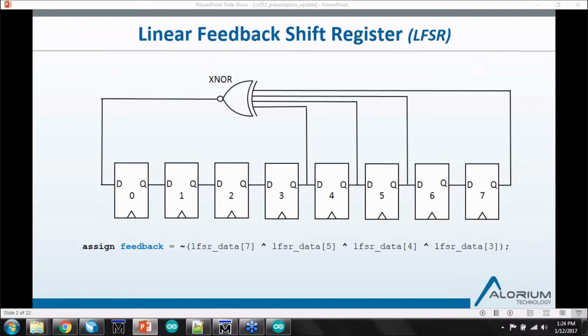For example, in verification or testing for chips, a lot of the stimulus generation uses LFSRs under the hood to generate pseudo-random numbers. And the cool thing about it, as you heard Brian refer to the seed value, is you can start off with a specific seed, however you fix these registers at reset time, and you'll get the same sequence of numbers every time from a given seed. So it's very powerful for predicting a string of numbers and generating a pseudo-random string.